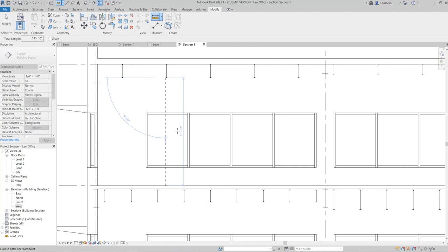This measurement tool is different from the dimension tool. Okay, this measurement is just temporary, but dimension is permanent. Okay, so we can measure wherever we want, and as you click for your next measurement, the last one is gone. So that's why we say it's temporary. And as you can see here, it's a split button. We have measure between 2 references and measure along an element, but most of the time we will use this first one.